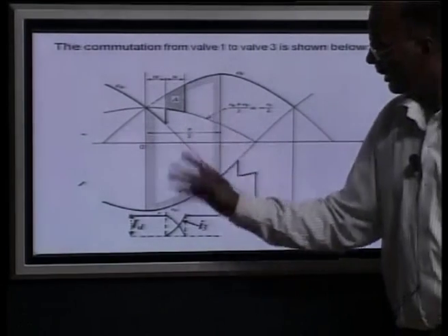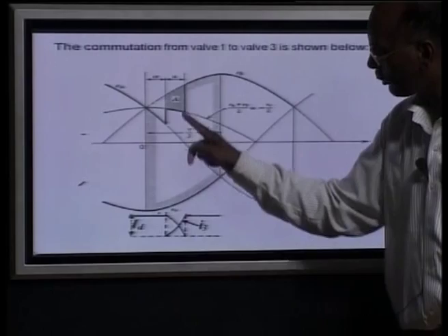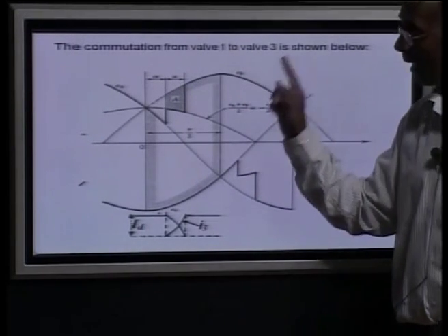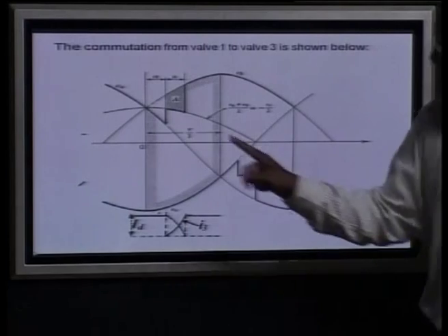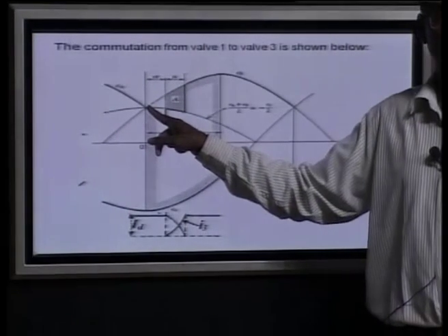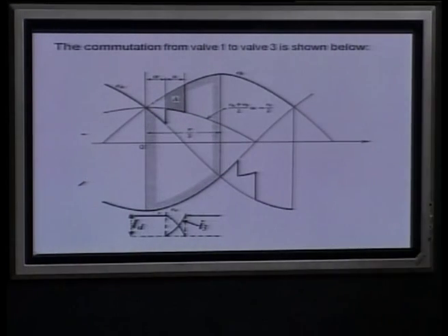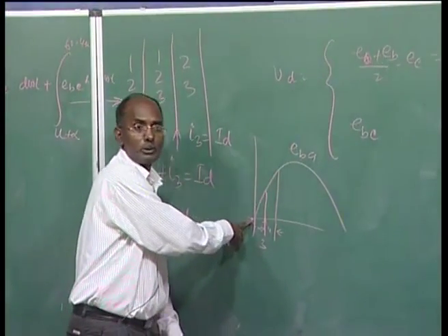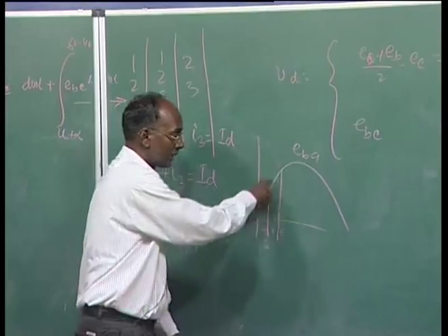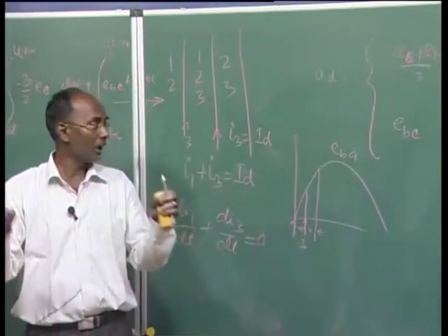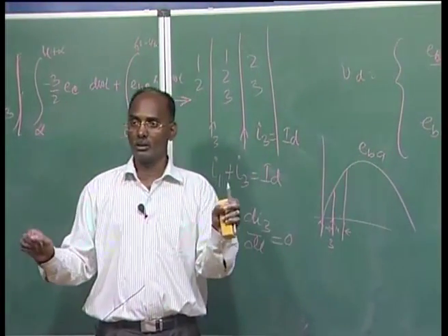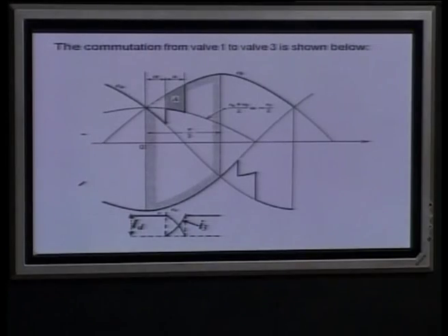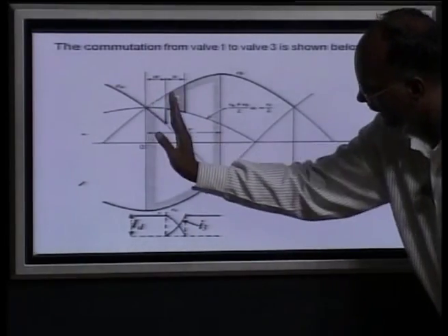So, if you are starting from here, then you have to take the phasors accordingly, but we took E_BA as our reference. E_BA reference was 0 here, because I said this E_BA which I am taking here is the reference as our omega t equal to 0, and because these are phasor voltages, I took E_BA as a reference. So, now we are just delaying alpha degrees.